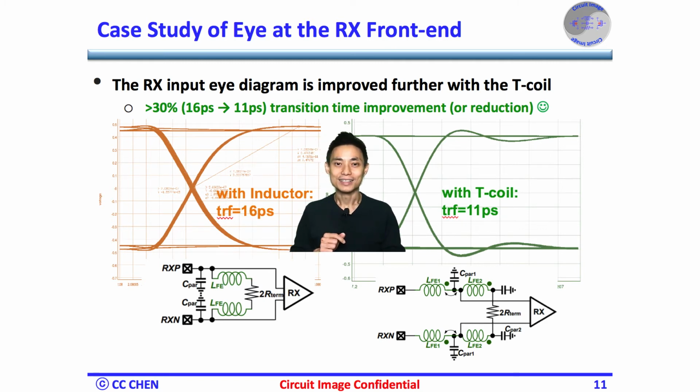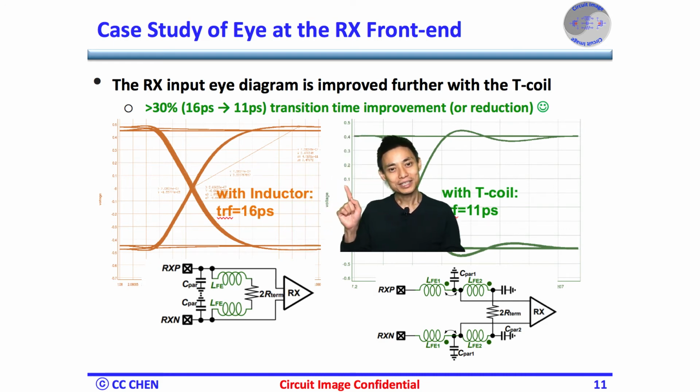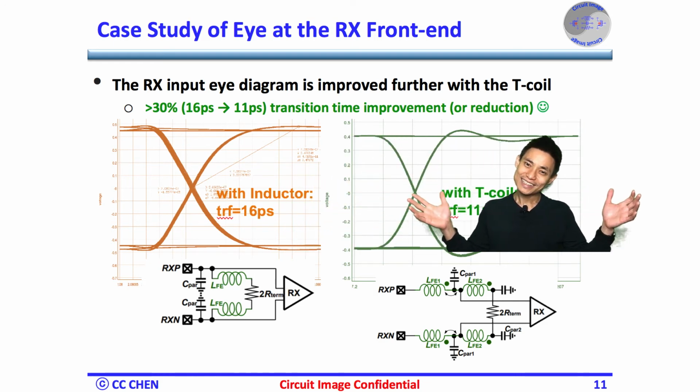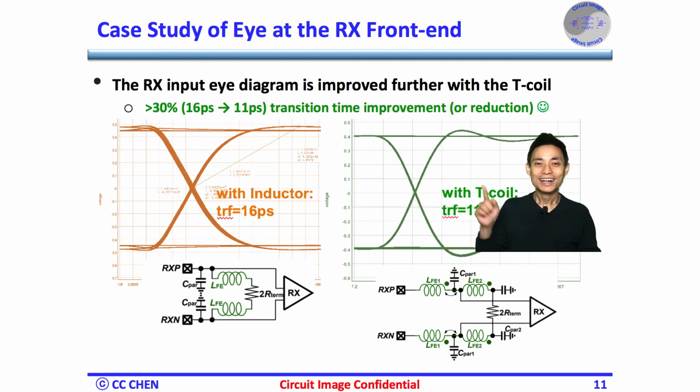But there's a little subtlety in the eye diagram. Could you notice it and make a guess? Yes, the ringing may happen with more coils, and we need to make sure the ringing settles down within one bit period, such that no intersymbol interference occurs. Again, this green eye is still fine, since the ringing settled down quickly within one bit period.